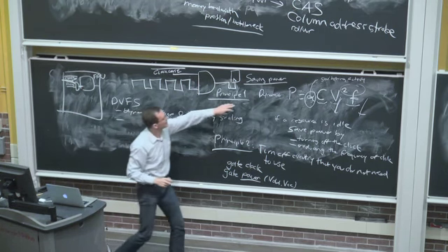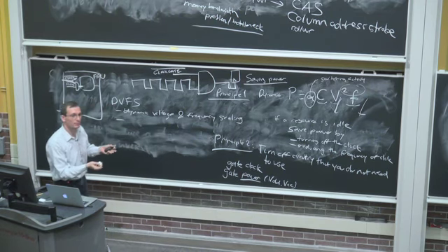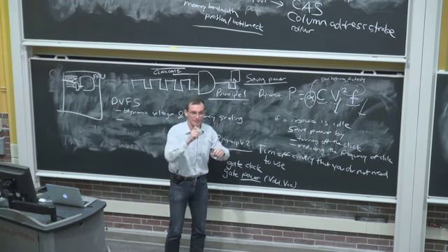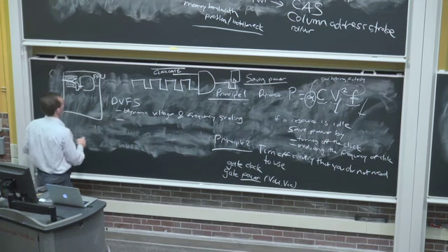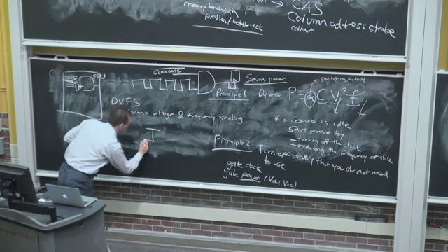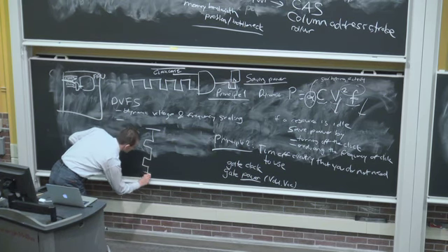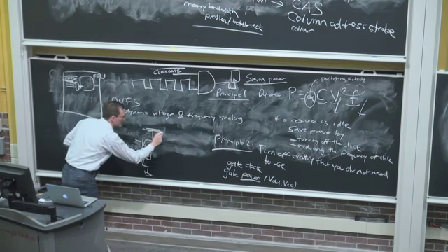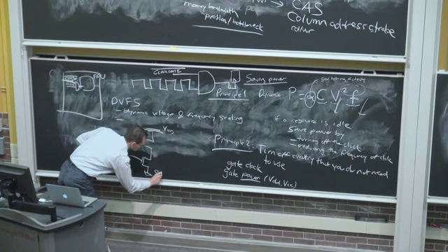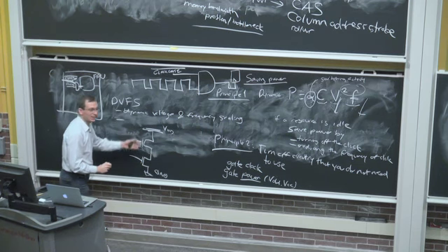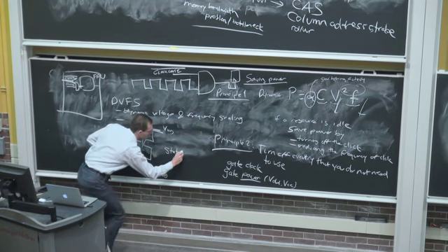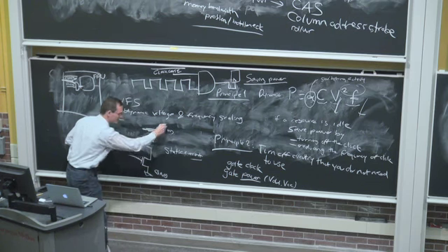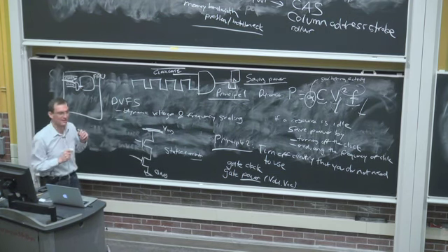How do you save static power? So static power is consumed when the circuit leaks, right? Even if you're not using the circuit, there's some leakage that happens through the transistor, right? Remember, I guess an inverter. You have basically, even if the circuit is not turned on, the charge leaks from, again, VDD to ground. There's some leakage or static current, if you will. And you can represent any circuit in kind of like this form. There's always a path from the VDD to ground that charge leaks.